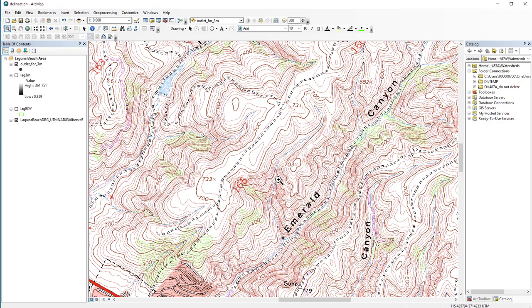So as you recall, V's pointing upward, or you acclimate your eye to the contour map, and V's pointing upward indicate the stream bed, and U's pointing downward indicate that ridge line or that watershed divide. It's this watershed divide that is what we're going to identify. It's that location that separates two basins. So if a drop of water is to fall right here, is it going to go into this stream network or this stream network? And that's what this ridge line allows us to identify.